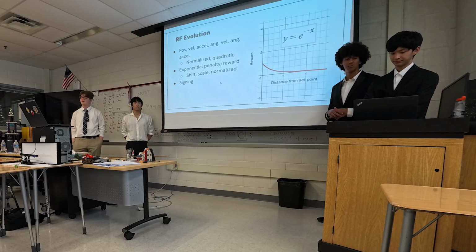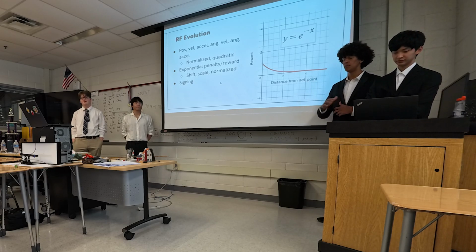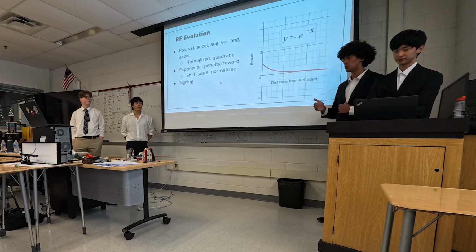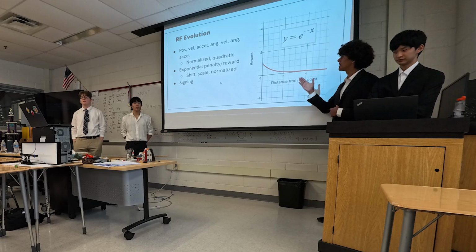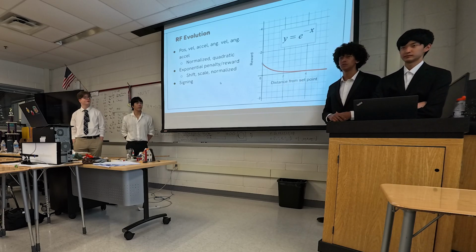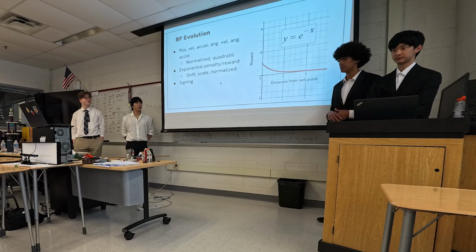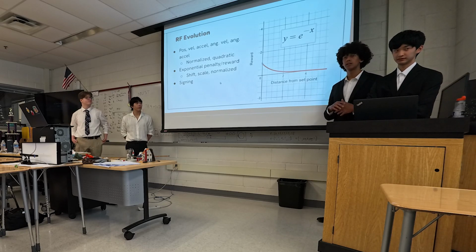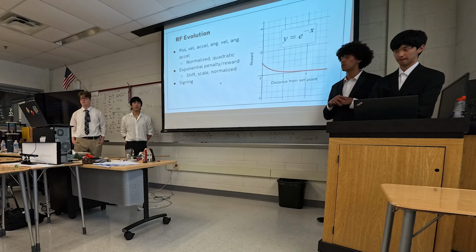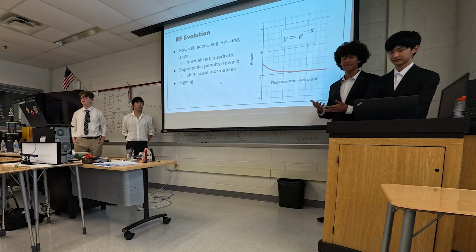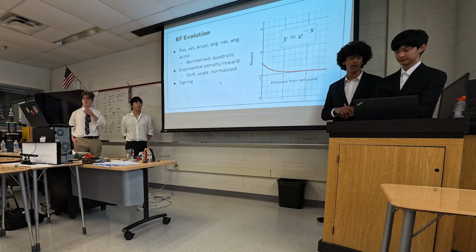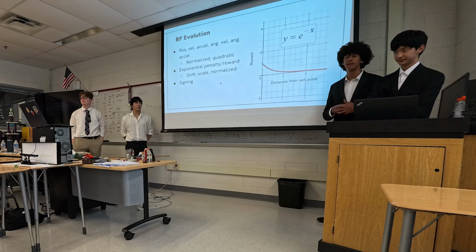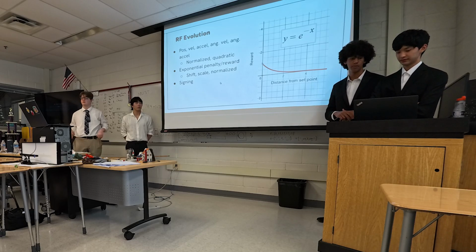And the reason we did that was because, imagine position. The position can take a value anywhere from -1 at the very left end of the beam to 1 at the very right of the beam. Whereas a parameter like angular velocity may be able to take values with much larger magnitudes. So naturally, if we are not normalizing or squaring these parameters, the reward function and the agent will apply a lot more weight to angular velocity as a parameter, whereas position is a much better indicator of how good we are doing in terms of the system.